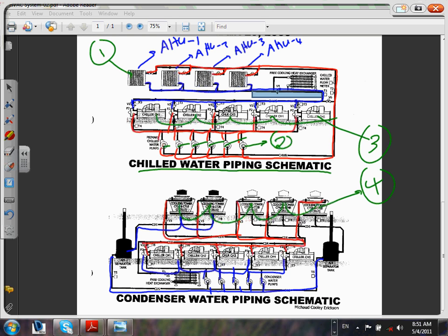And when you blow air outside the building through hot water, you're getting the heat out. You're basically cooling the water, right? You're getting the heat out of the hot water into the environment. Then it cools down. And you can see how they cool it down again. Right here, it cools down and goes back to these tanks that take it back again to the chiller.